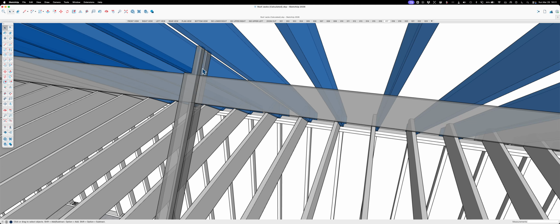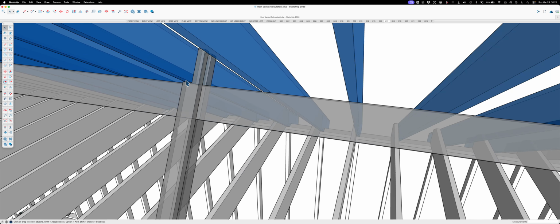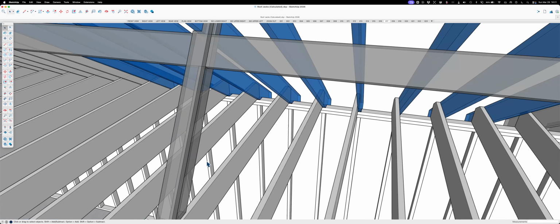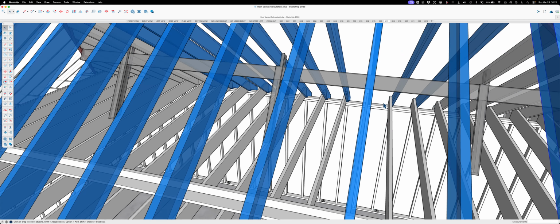And then I come back with another 2x4 that I've notched out 1.5 inches or 2 inches or whatever, so that I can shoot into the rafter again, shoot over where I've got the purlin nailed, and then all the way down, boom, boom, boom, into this other purlin arm, so that they're sandwiched on both sides. And this will never, in a 140-degree attic, it'll never twist or anything. It'll last. Everything's tied in nice and solid.